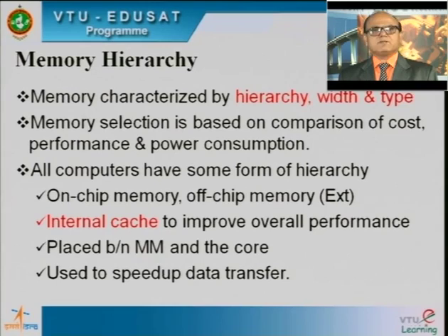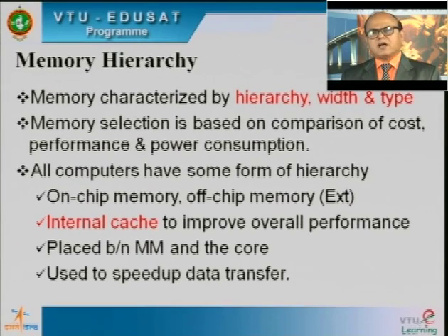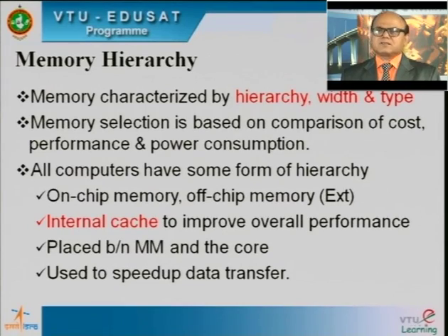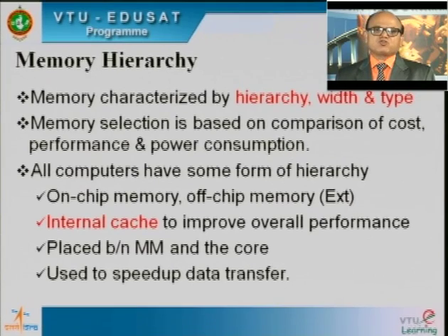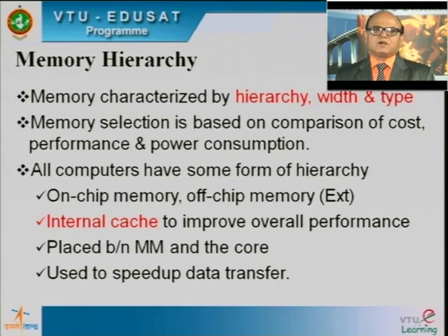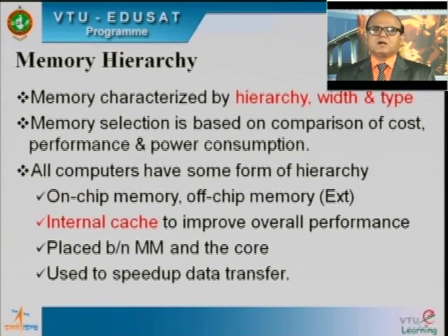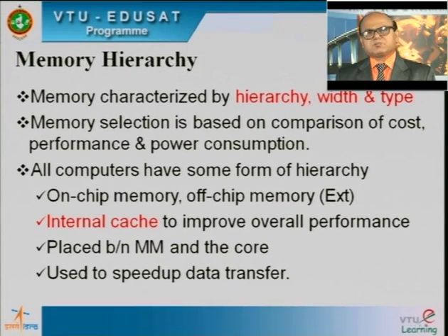So whenever we design embedded systems, we select memory of the exact requirement, we calculate and then use accordingly. Wherever cost constraints exist, if the system permits, we use slower memory. A smaller memory always leads to lesser power dissipation.